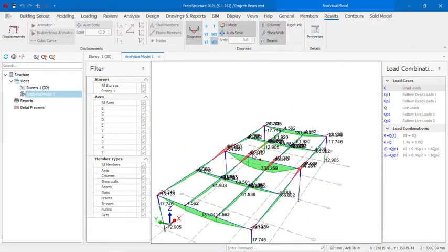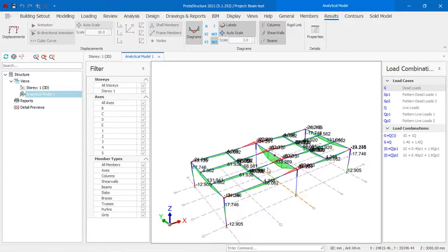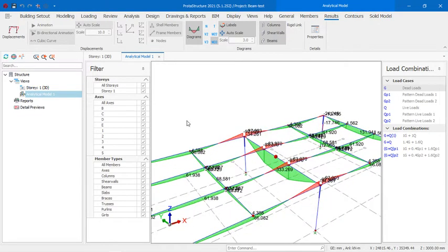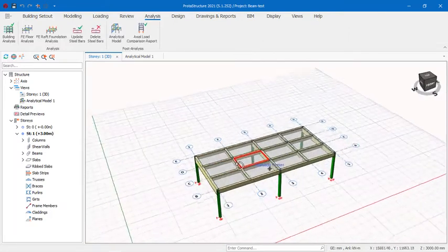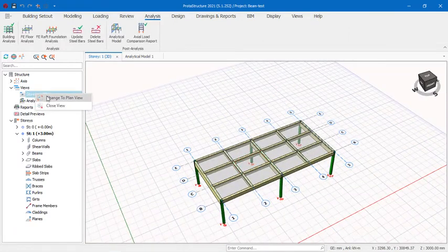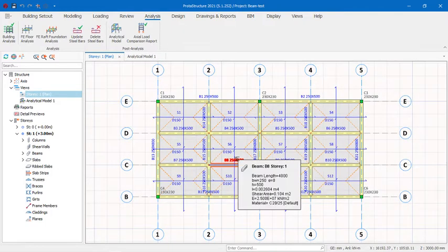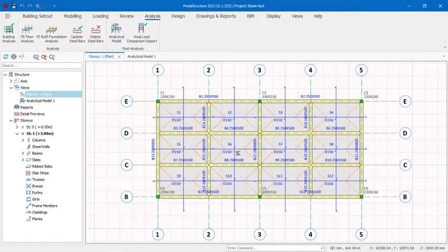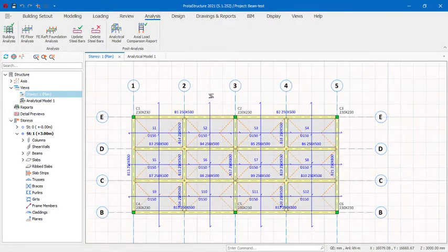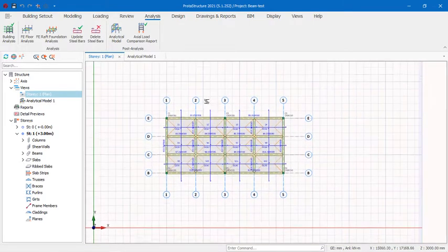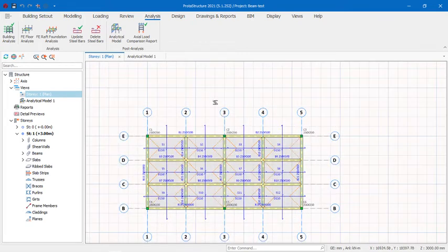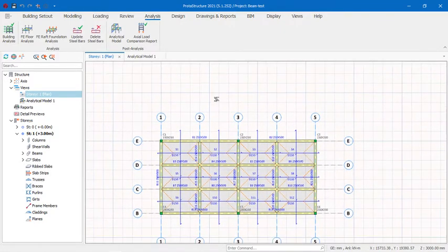Now note where I stress that they said you should size your beams appropriately, based on how you idealize, how you want to predict that your structure will behave. Now the question that arises from this assumption is: what is my construction technique? If I analyze as a 3D effect and I'm going to construct in a different way, then what is the effect on that?